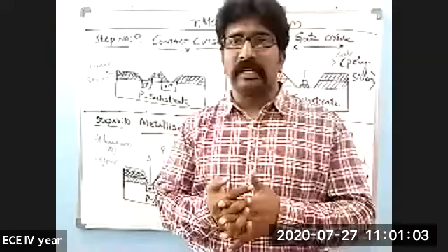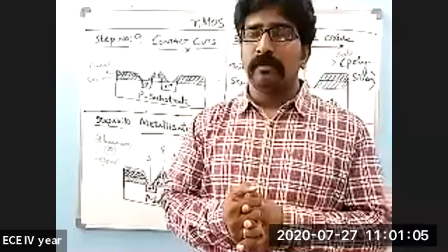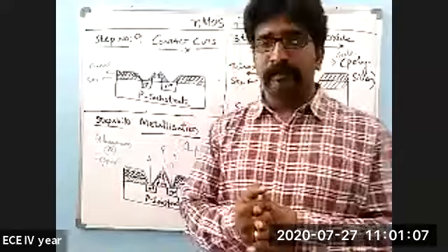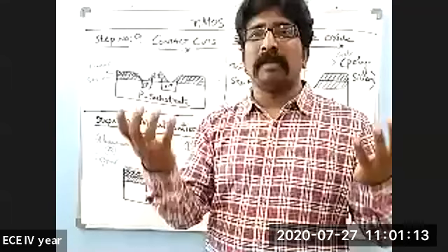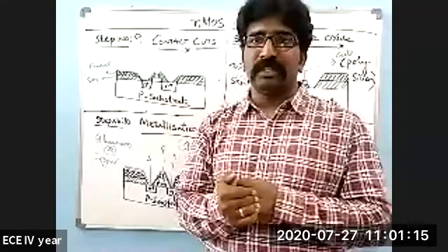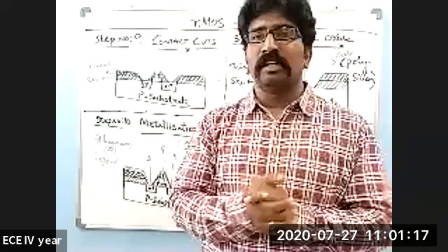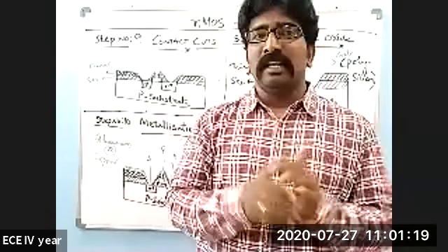That is, after etching again, they keep the metal only where it is needed and remove all the rest. So now in this NMOS fabrication, we have studied 10 different steps. Yeah. Okay, sir. After that, passivation will be done. Okay. Different chemical techniques are there to passivate the integrated circuit, to protect the integrated circuit from any kind of harm from the environment.